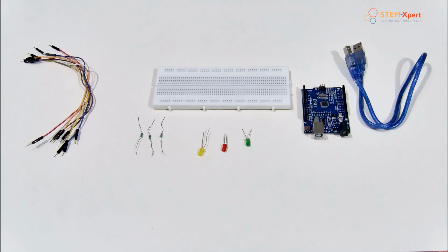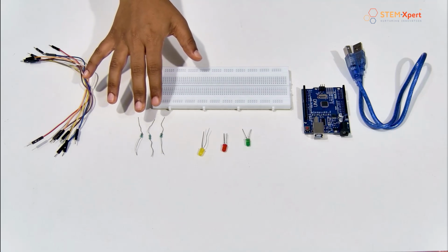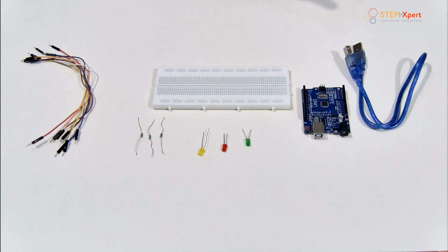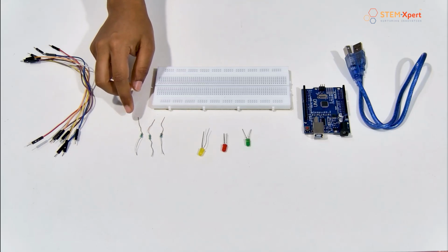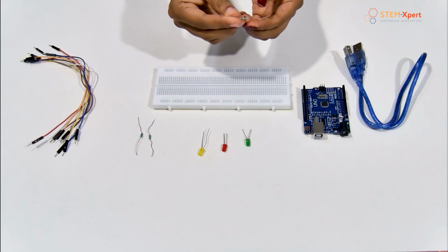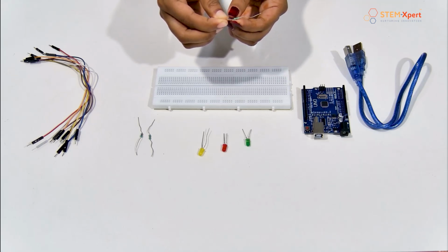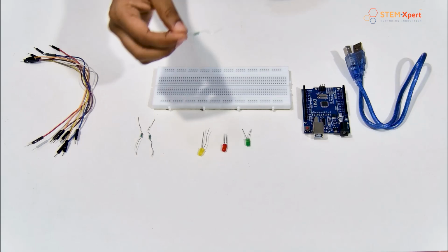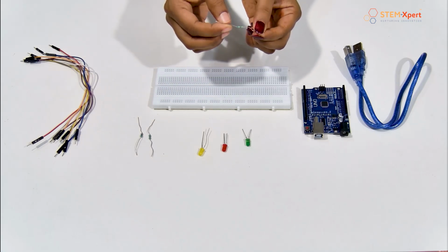Done? Okay. So here we are using 3 LEDs and 3 resistors as output components, and we will control the LEDs using text coding. Make sure that you have the 330 ohm resistor in your kit, orange, brown. You need 3 330 ohm resistors. Just check the color code: orange, brown. The last color may be silver or gold. Here we have gold. No need to worry about that last color, it may be gold or silver. You just check the first 3 colors: orange, brown.